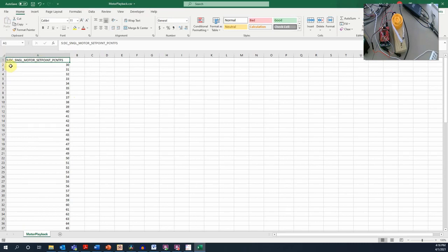S stands for stimulus. So this tells the playback feature that we're going to hijack this signal and inject these data values. An R colon means response. So that would mean that we're going to read back any variables in columns that are listed as R colon, meaning response. Now in this case, we're just going from 30 up to 77 and then back down to 30. Pretty straightforward.